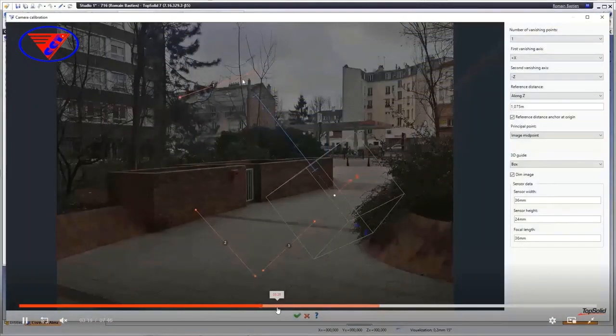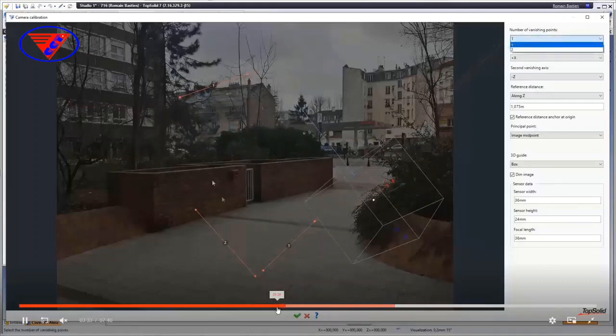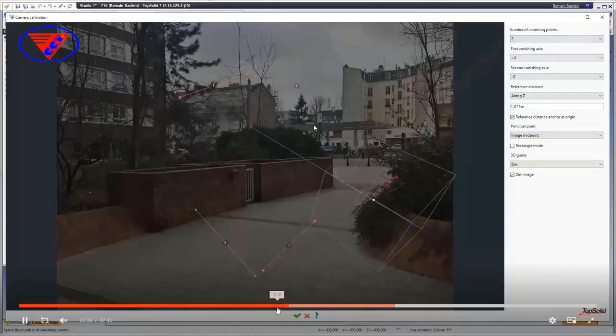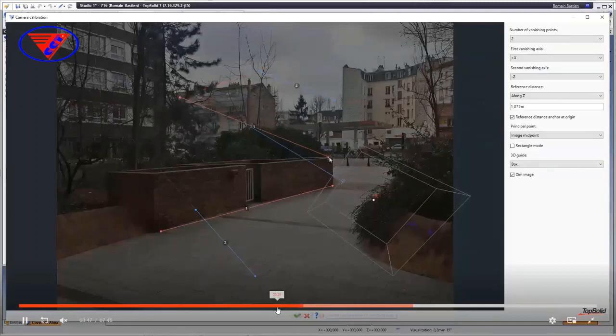Go. And now what's happening is we're basically using a specific tool. It's called camera calibration to define where our zero reference is on this image and to define the orientation of the x-axis and the y or the z-axis, as well as a scale. And you can see here it's done just by dragging these objects around to define how everything is. And so this is the x-axis that we're defining right now. You can see that wall isn't so square, but it's not so important.